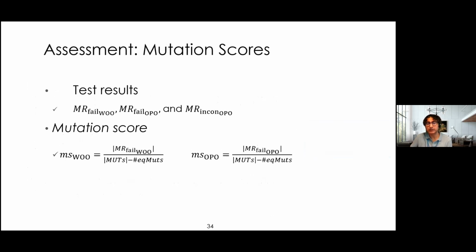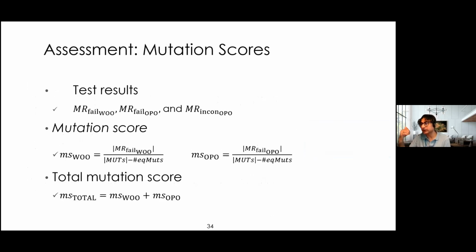The mutation score is basically just a formula. It tells you how many, so let's say I have 100 mutated faults with add, remove, and those kinds of gates, I just need to simply see how many of those were found by my test cases. We call this the mutation score, which helps us find how effective my test suites are in finding those faults.